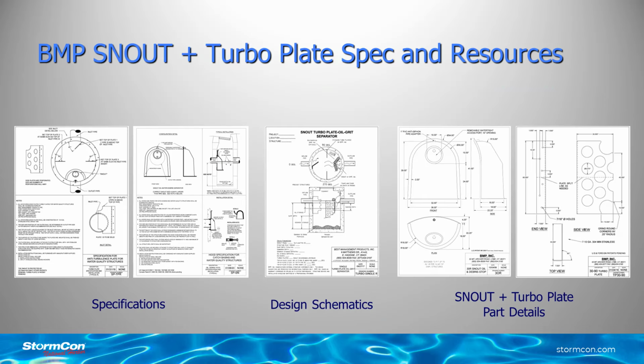So now we're in the situation where we know we want to do water quality in a structure, and we're going to use a hood to cover the outlet pipe to get that skimming effect where we're skimming off the floatable debris, and we're letting things sink to the bottom. But we want to ramp up our sediment, our TSS removal.